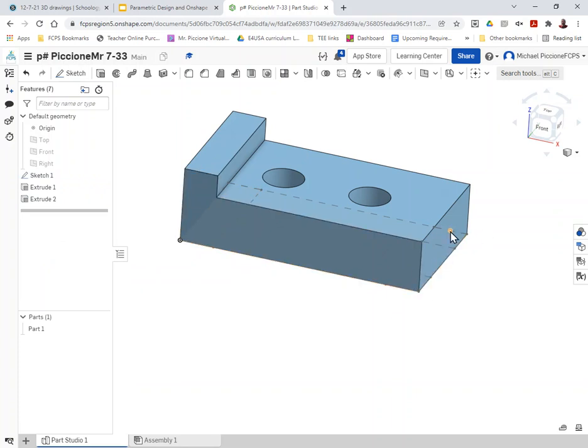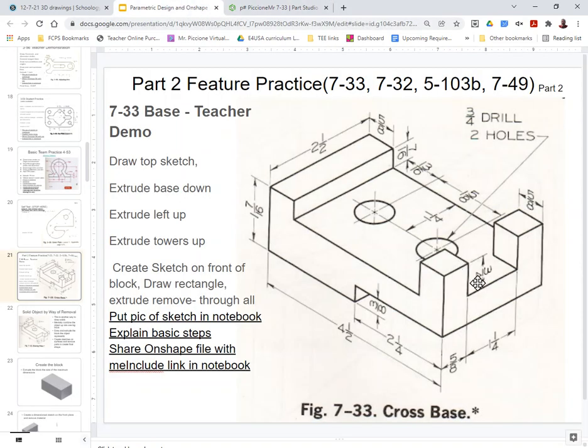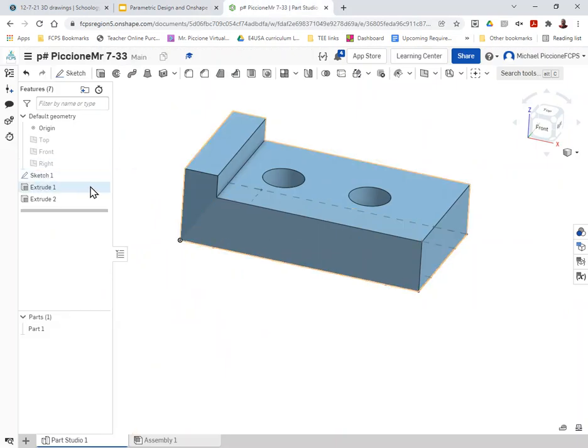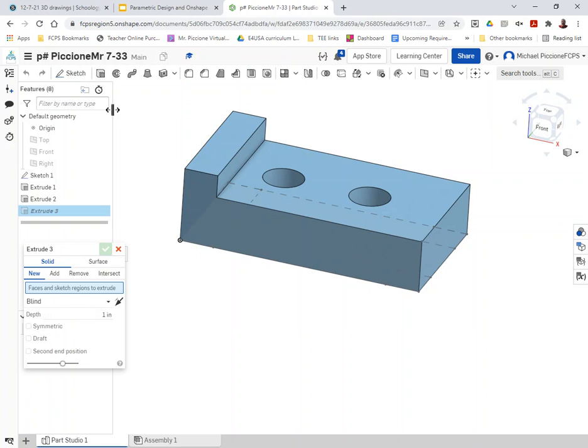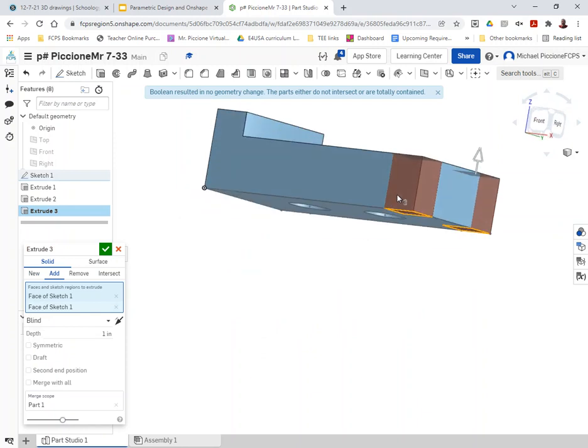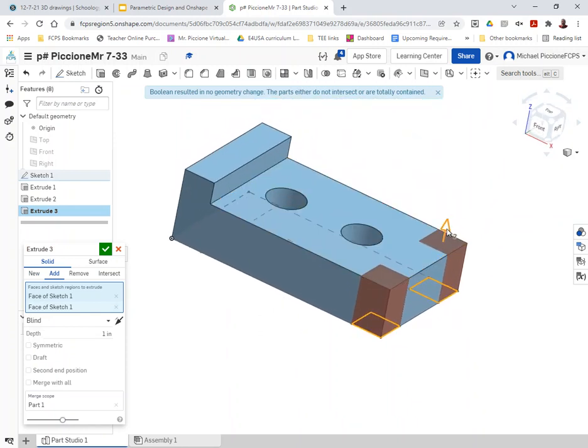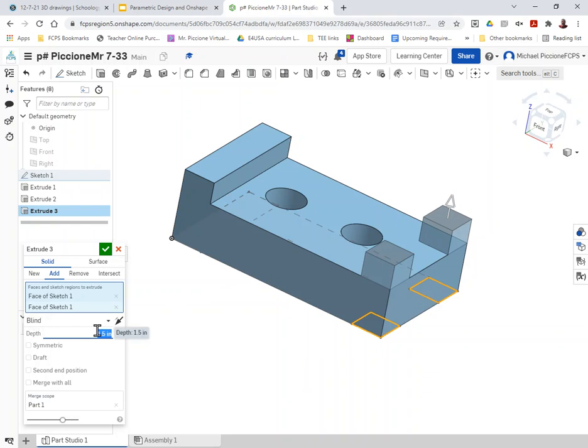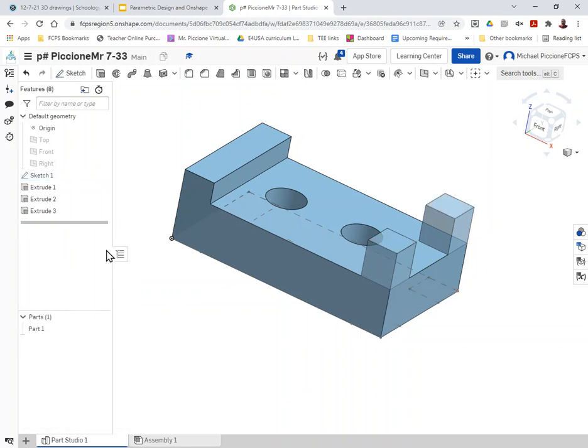Now I can do the same thing for the squares over here, except they go up 3/4 past the surface, and we know the surface was 1, so I can just say 1 3/4. Extrude, turn it over so I can click the shape, square 1, square 2, pan down a little bit. Now I can drag that up a little higher to see what it's going to look like, and I want to type in 1 3/4. Tab, and click OK to save.